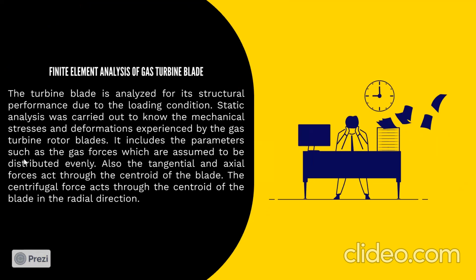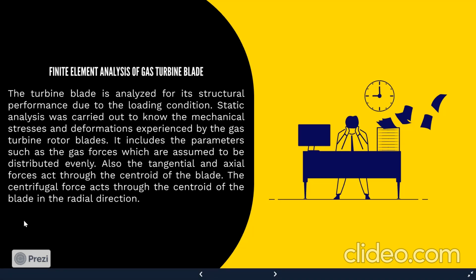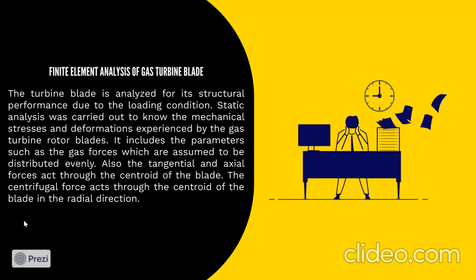Static analysis was carried out to know the mechanical stresses and deformation experienced by the gas turbine rotor blades. This includes parameters such as the gas forces, which are assumed to be distributed evenly. Also, the tangential and axial force acting through the centroid of the blade, and the centrifugal force acting through the centroid of the blade in the radial direction.